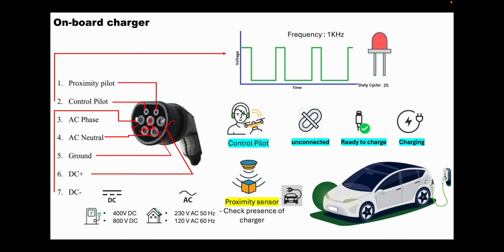So these 5 pins that you see are also bigger in diameter because these carry the power supply, and that means they carry a good amount of current, and that is why they need to be thicker, to offer less resistance and produce less heat during the charging process.